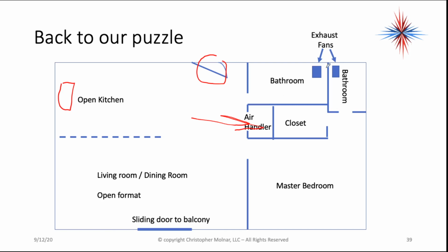Both these restrooms had exhaust fans. They're mechanical exhaust fans. However, in a high-rise building like this, the mechanical exhaust fans will always be exhausting air whether or not they're running. If they're running, they just exhaust slightly more air. If they're not running, the air is exhausted based on pressures.